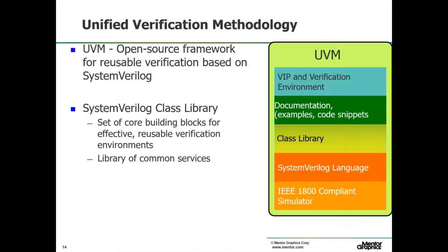And so what really is the UVM? It's built on the SystemVerilog language. It will run on any SystemVerilog compliant simulator. And it's basically just a set of class libraries for things like drivers, monitors, scoreboards, checkers, and vanilla versions of all these things are built as a class library. And then the user uses object-oriented class extension to create their test bench out of these things.